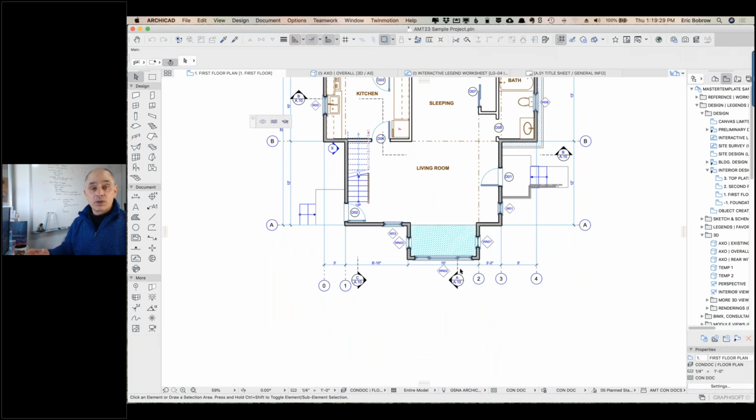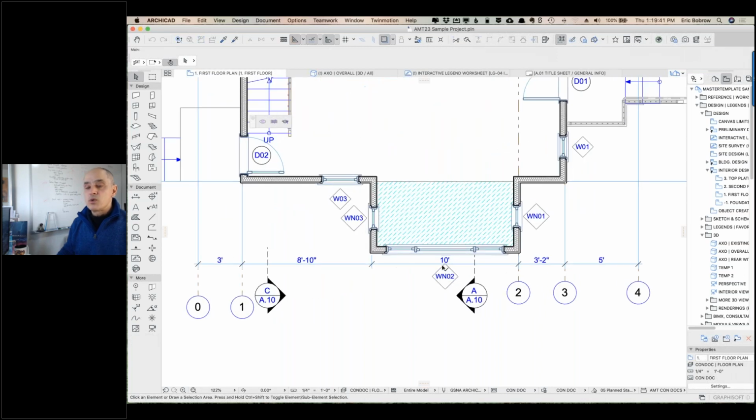The auto dimension tool is a great one because you can select a whole bunch of walls and have it automatically place the dimensions at specific distances between each other. But there's no quick, instant place. You have to actually measure it. So for example, if I drop the dimension tool, so now I'm ready to put in dimensions, and I say click on 2 points.